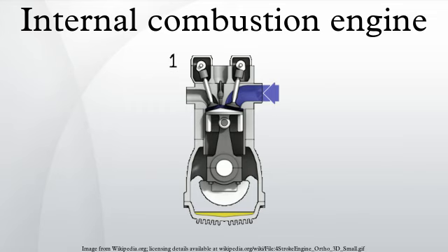Operation. As their name implies, 4-stroke internal combustion engines have 4 basic steps that repeat with every 2 revolutions of the engine: 1. Intake suction stroke, 2. compression stroke, 3. power expansion stroke and 4. exhaust stroke. 1. Intake stroke. The first stroke of the internal combustion engine is also known as the suction stroke because the piston moves to the maximum volume position, creating a drop in pressure. The inlet valve opens as a result of the cam lobe pressing down on the valve stem, and the vaporized fuel mixture is sucked into the combustion chamber. The inlet valve closes at the end of this stroke.